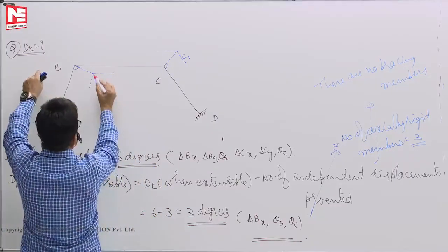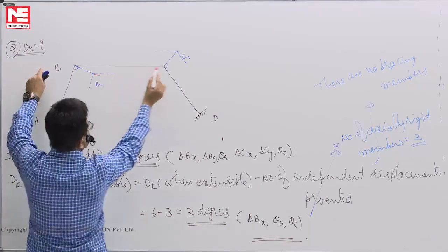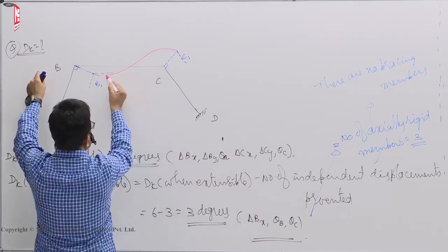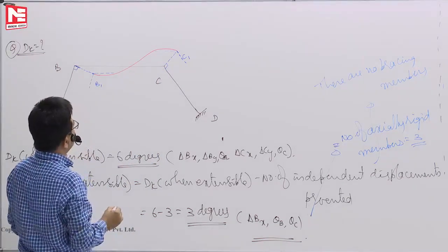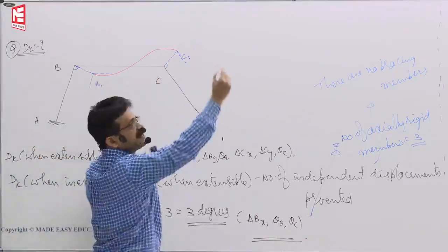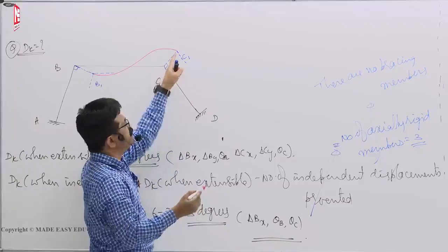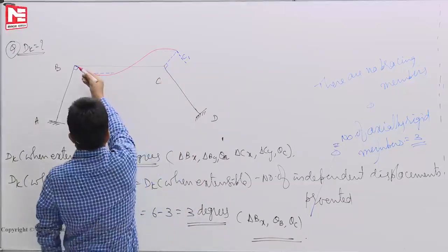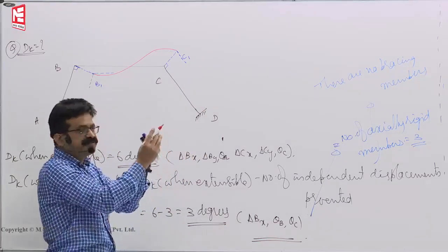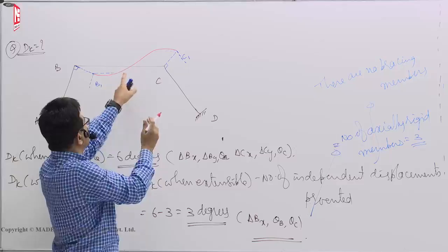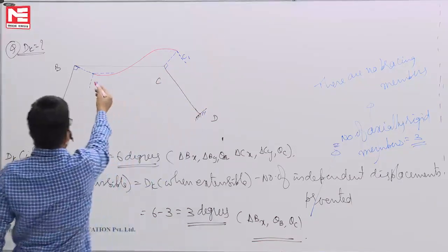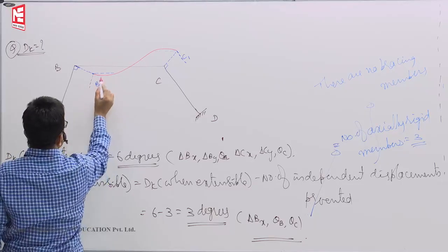Supposing that this rotates here by theta b like this. Here also it rotates by some angle. The zoomed view we have drawn, that's all. Like this it rotated, say. Because I have drawn so high a value so that everybody can see, it looks like a cable deflection. But actually CC1 is very small, so almost like that only will be there. For the sake of seeing the problem properly, compared to this and this, they are not drawn to scale, so I have drawn so much here. Now here if it is sagging, here also it must sag.